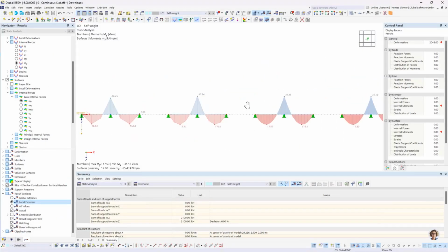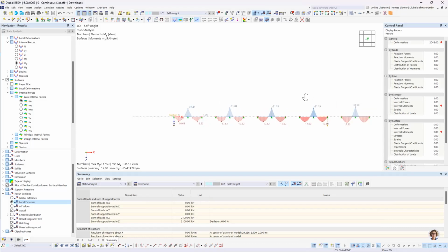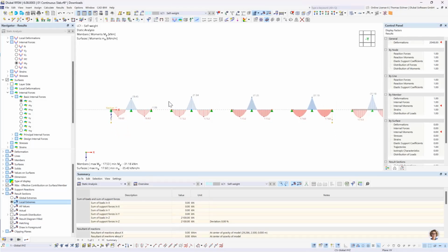So here, maybe we can look at that quite a bit better. So here this 28.45 versus the 31.818. Yeah, almost 10%. That's not quite good. So that's the problem with this coarse mesh. We will lose exactness in the results.